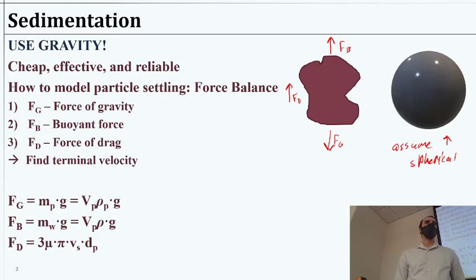So in this case, we're going to have the same dynamic, and the drag will increase as the speed of the particle increases. But the force of buoyancy will also be pretty important. So those three forces, and essentially what we want to do is find the terminal velocity. So we'll reach a terminal velocity once the force pulling downward is equal to the sum of the forces pushing upward, right? So that's pretty basic here.